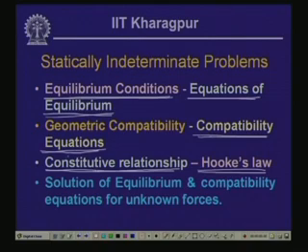So, these three are the essential parts for the solution of statically indeterminate problems. First one is the equilibrium equation, second one is the compatibility equation, and third one is the constitutive relationship, which gives us the relationship between the strain and the stress, and thereby we can write down the equations in terms of forces.